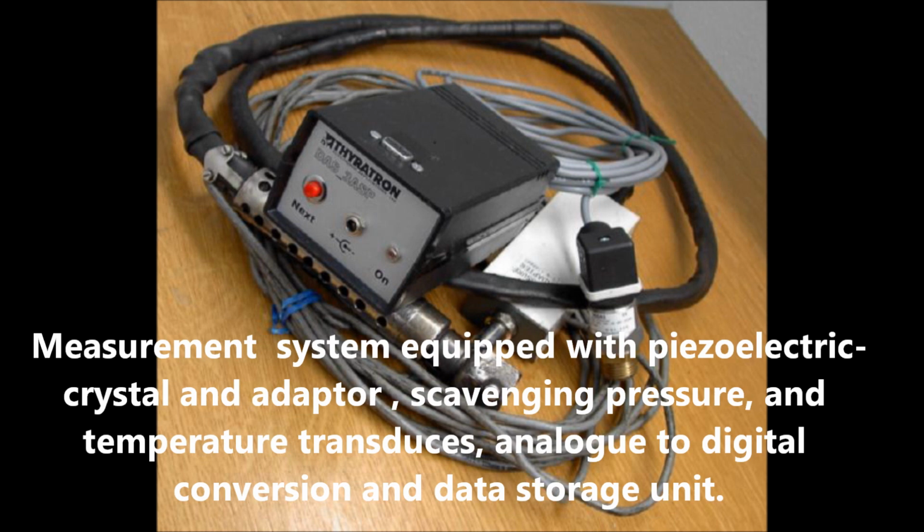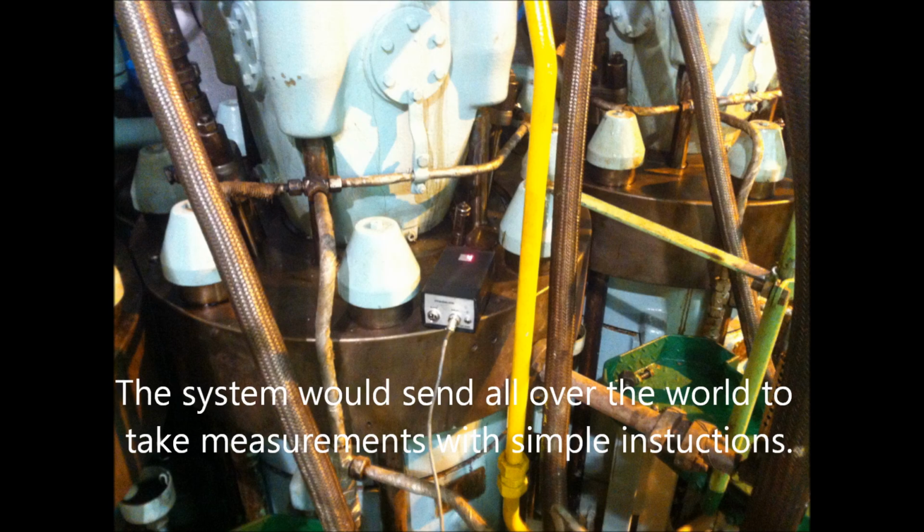The measurement system is equipped with a piezoelectric crystal and adapter, scavenging pressure and temperature transducers, analog to digital conversion, and a data storage unit. The system can be sent all over the world to take measurements with simple instructions.